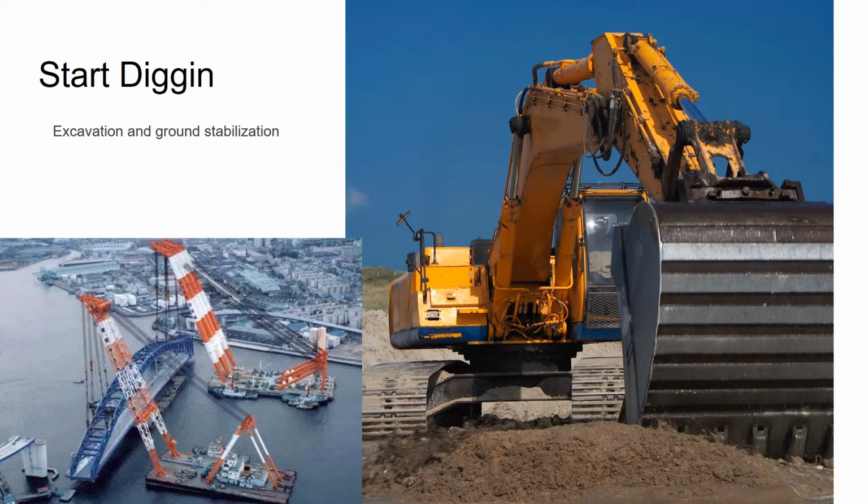Fun little fact here, those 2 water cranes, those are water tower cranes, and there's only a handful of them in the world. So for building a big bridge, these are the pieces of equipment that are used. You can see they have that big chunk of a bridge. It's all been made right off the water. It's been made on land, and then it's been transported, and these cranes are going to lift it and set it onto these supports. So they're not actually building out from the support to the other side. They're just basically putting a big piece on the supports that they've made. It's a lot simpler process, and this is how a lot of bridges are made, in big pieces.